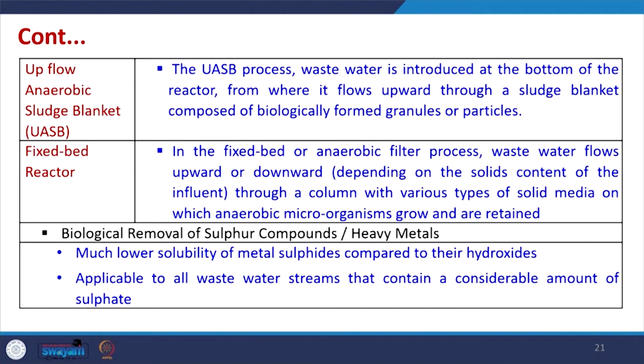Now, upflow anaerobic sludge blanket reactor is similar. It is very common. It is commonly called as UASB reactor. In the UASB process, wastewater is introduced at the bottom of the reactor, from which it flows upwards through a sludge blanket.